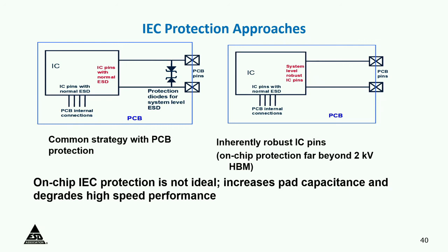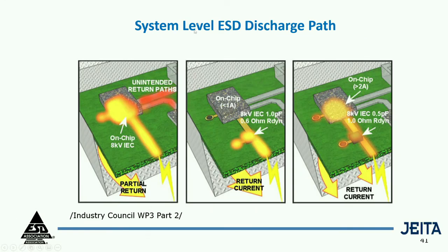That's the reason people recommend trying to terminate it outside the system right here, so that only some energy goes in and you deal with whatever energy goes in. So the way to do that is, if you put an IC on chip, then there are a lot of return paths, and you're trying to terminate such high energy into this thing, which is not a good thing. But what you do is put it externally, so everything is terminated, and only a small amount of current goes into the chip. Once you do that, you are doing it much more efficiently.